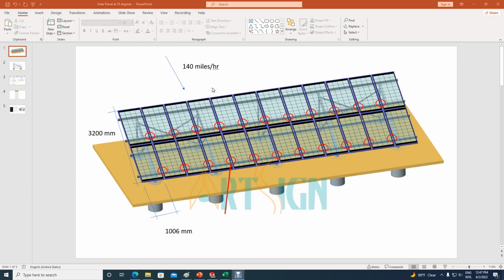Somebody asked me to do a lift and drag analysis on some solar panels that he's putting together. He sent me an idea, a kind of croquis of how things will look in a sketch. Within this sketch, I have back winds of about 140 miles per hour. These are hurricane winds, right? They come through the back of the solar panel installation, and basically this wind will try to make the whole thing look more like an airplane wing, with winds of this magnitude.